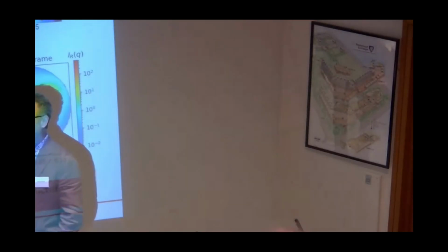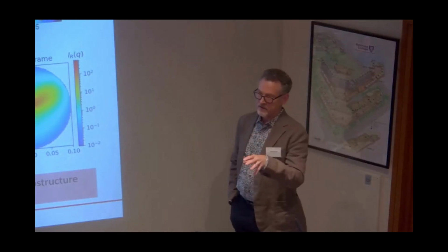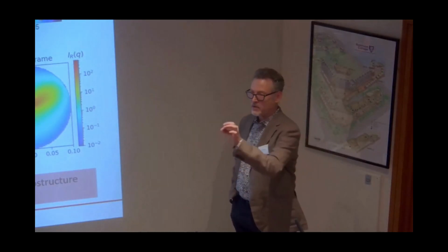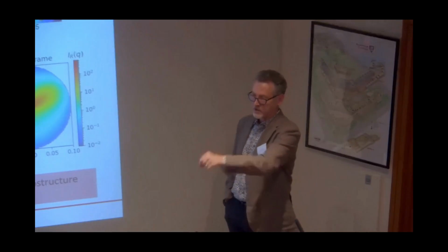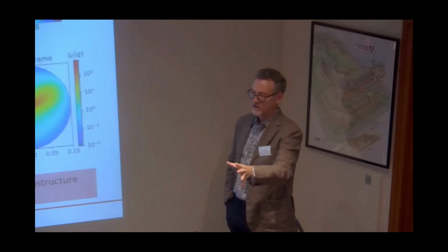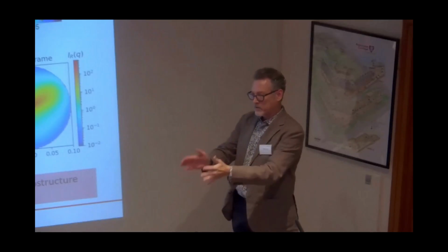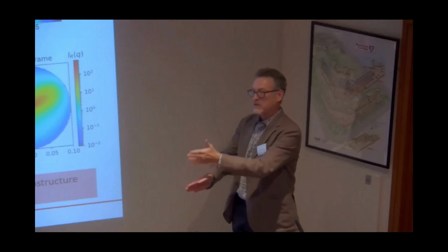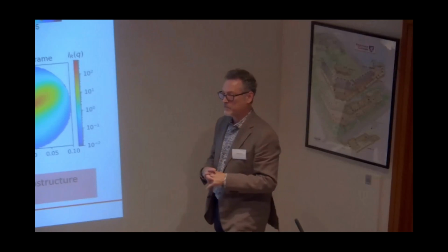Even then, you can only get the stresslet, the deviatoric part of the stress. Unless you have pressure or normal stress measurements somewhere, there's a whole part of the stress that you don't have access to. So you're going to need rheological data, with first and second normal stress differences, and microstructure to get a full description.